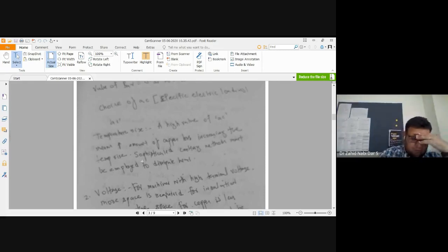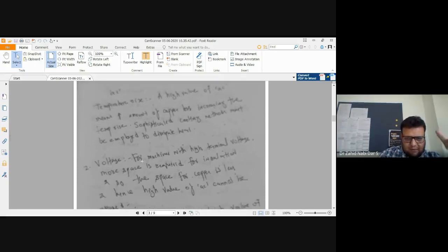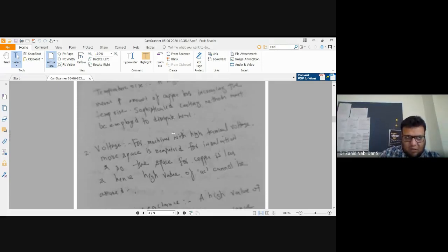But again, I have told you in class time and again, I am telling you once more, that your transmission lines are predominantly inductive, otherwise they would also heat up. So one thing to be noted here: sophisticated cooling methods must be employed to dissipate heat. In your alternator or your transformer, you have cooling tubes, and you have a fan in every machine. In induction machines also you have a cooling mechanism, because the temperature should not rise above a certain level, otherwise the insulation starts to burn, and if the insulation continuously burns, it will result in short circuit.